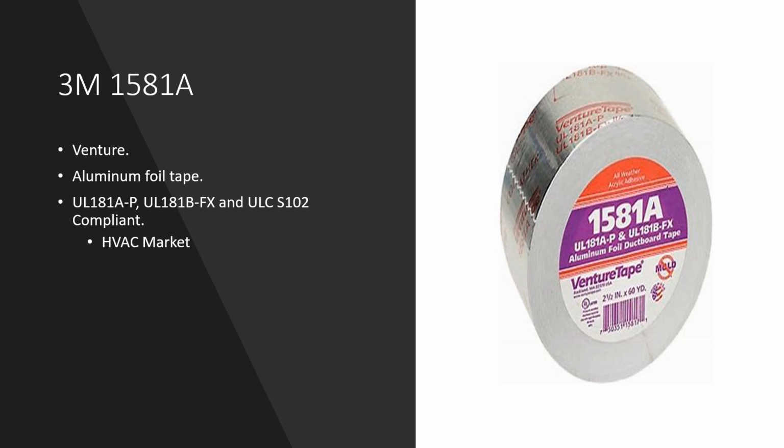For duct applications, the 1581A foil tape is our go-to. It has a UL 181A rating and UL 181B rating, which is needed to cover the seams in HVAC ducts. It is labeled so code enforcement officers can walk through a new building under construction and see that rating so they can sign off on it.